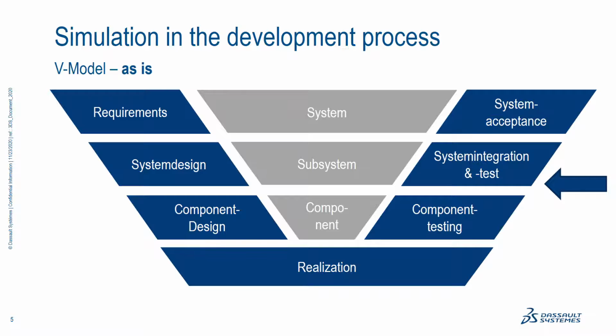So what's the simulation guy doing? He's importing the data, usually even data like STEP or other neutral formats. And the first thing the simulation expert has to do is usually heal the geometry. He has to remove many, many details because he doesn't need them.